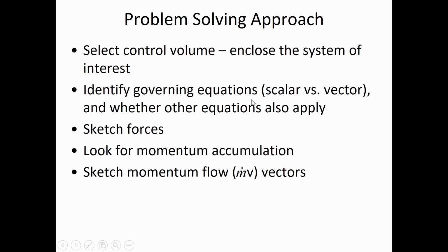You apply governing equations. The governing equations that can be used in problems like this might have to do with changes in pressure due to changes in velocity. So then the governing equation you'd use is Bernoulli's equation. Sketch the forces that are required to hold the system steady and look to see if there is momentum accumulation possibility. I think in most cases we'll find in our problems that there isn't momentum accumulation.